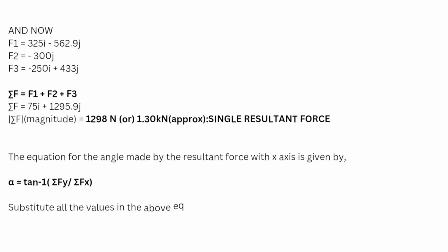The angle made by the resultant force with the x-axis is given by theta equals tan inverse of summation of Fy by summation of Fx. If I substitute the values in the above equation, I will get theta as 86.7 degrees.